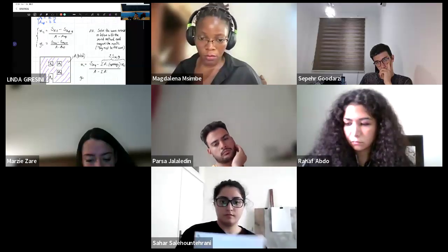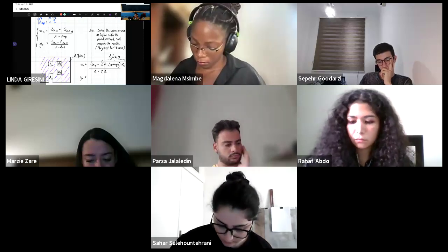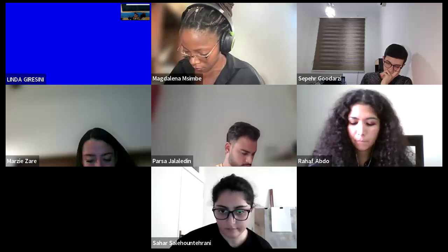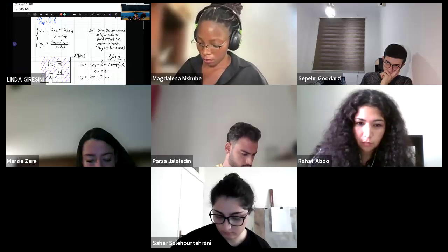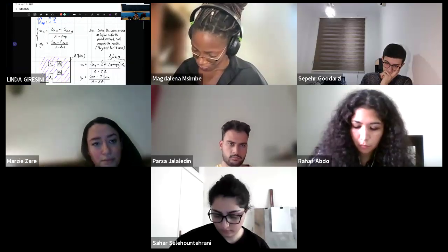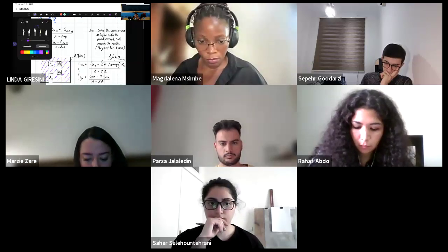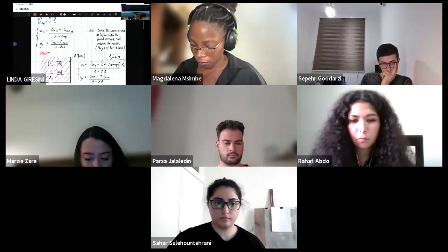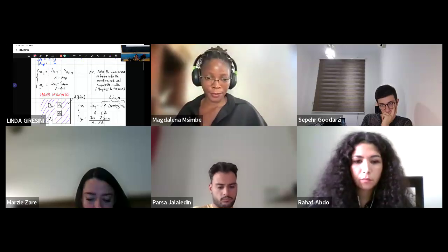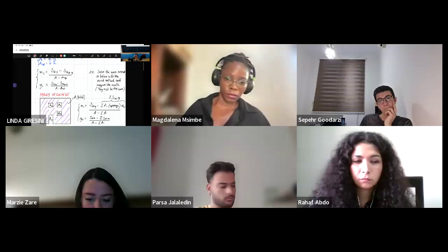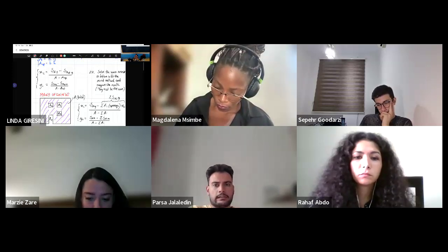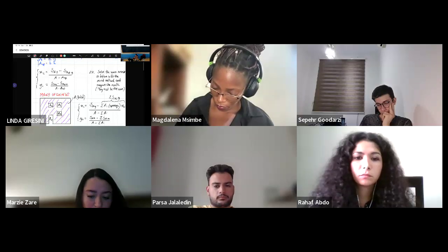And just for completeness, and then we stop. YC is equal to S_AX minus the sum of S_AI, divided by the total area minus the sum of the openings. So that is valid in case we have many openings. This is, of course, the easiest way, because if you proceed with the first method, it will be very long, probably impossible, because if your openings are not aligned, then it's very difficult to do.